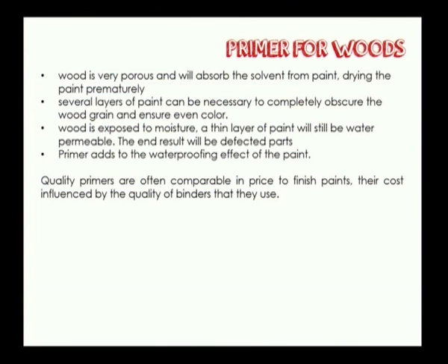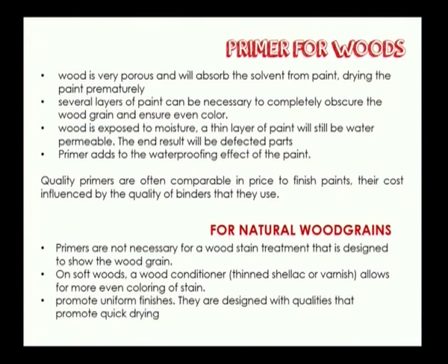So, for this reason, primer is very important when you are painting or giving a protective coat to the paint. Now, quality primers are often comparable to price in finished paints, the cost influenced by the quality of binders that they use. For natural wood grains, primers are not necessary for a wood stain treatment that is designed to show the wood grain, because you have varnish and varnish itself will act as a primer. The first coat of varnish you put, it will itself act as a primer.